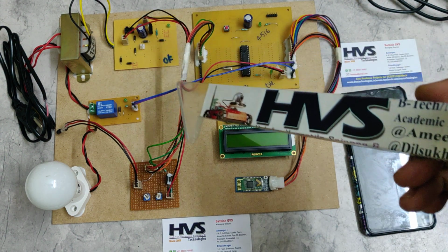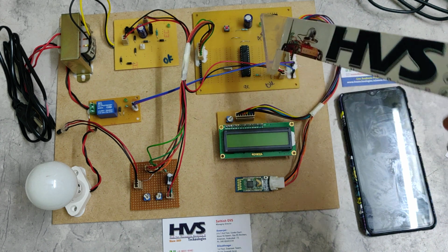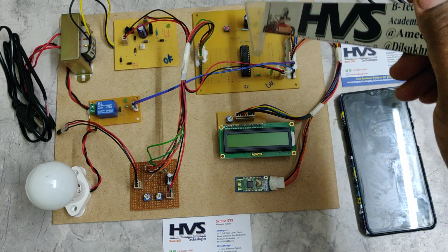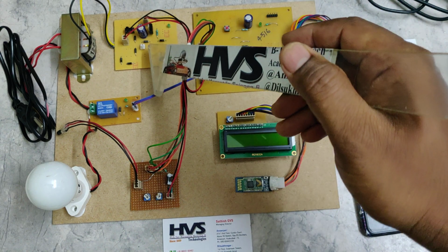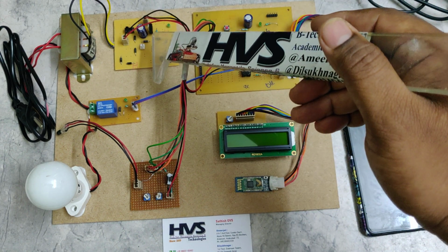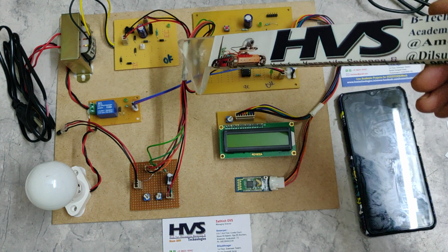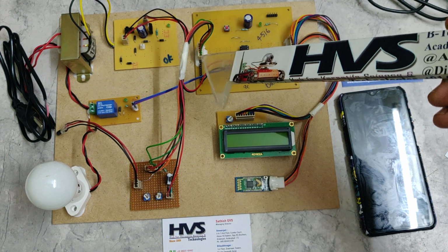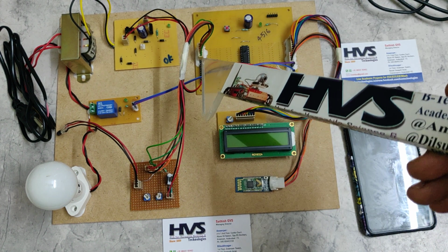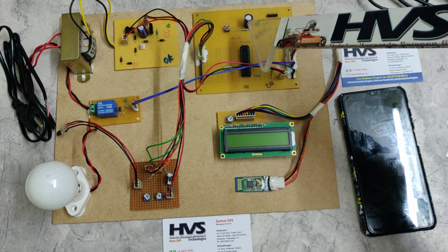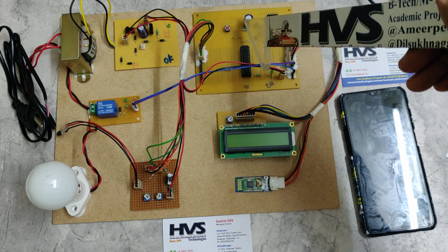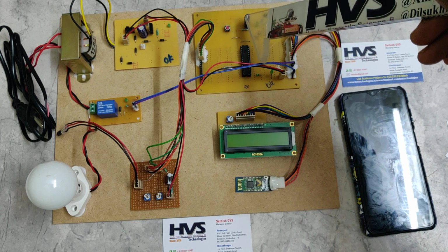And once we provide the power supply to the PIC microcontroller, there will be a capacitor. The capacitor's purpose is, though we are regulating the input voltage and getting DC 5 volts, after regulation also there will be a chance of pulses. So in order to remove the pulses and ripples in the DC 5 volts power supply, we are making use of this capacitor, and this capacitor will remove the pulses.